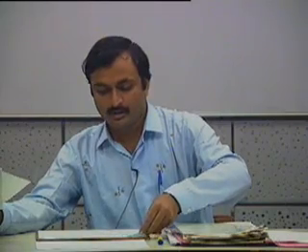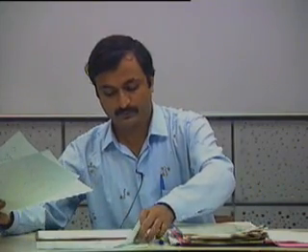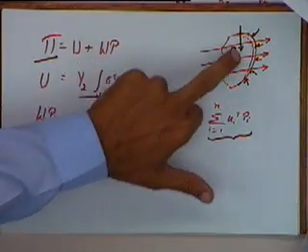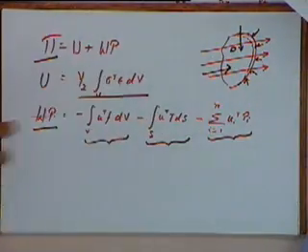Now, aren't we taking strain energy into account in the work potential equation? Because work is done against deformation, I mean work done for it to get deformed. That is the first term of the work. No, work potential is the work done against the external forces. Strain energy is whatever energy is retained inside because of the strains in the body. The two are because of two different terms, and the sum of the two will be the total potential energy.